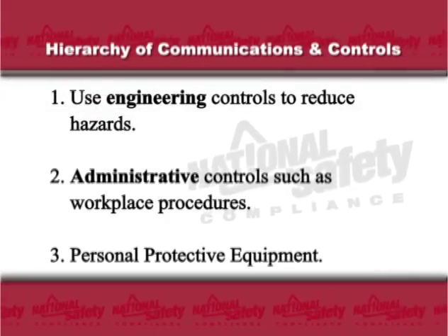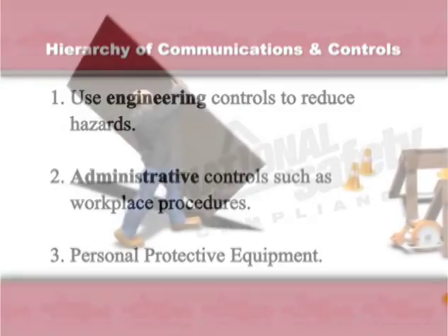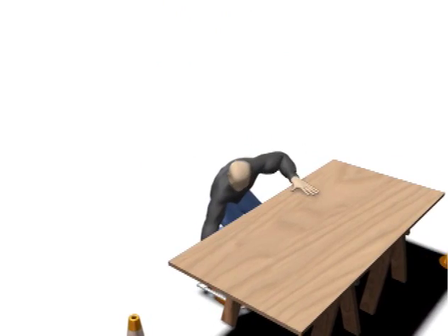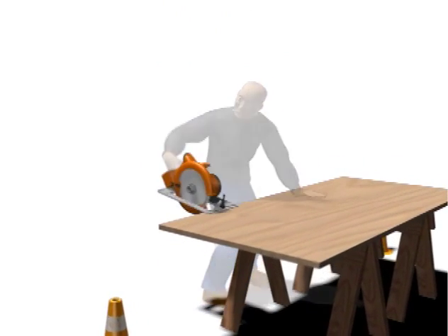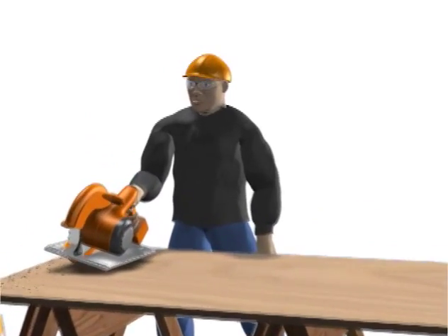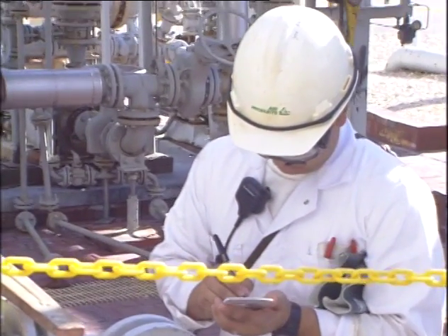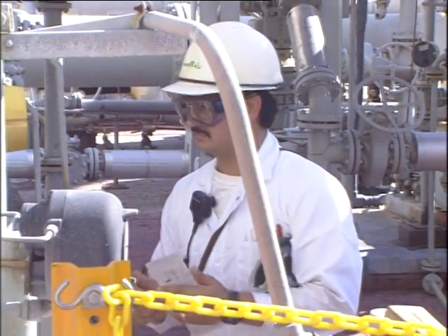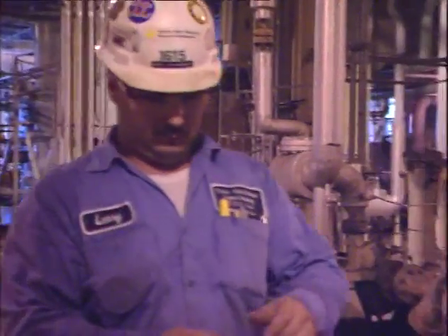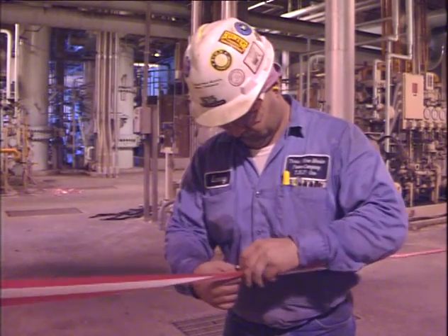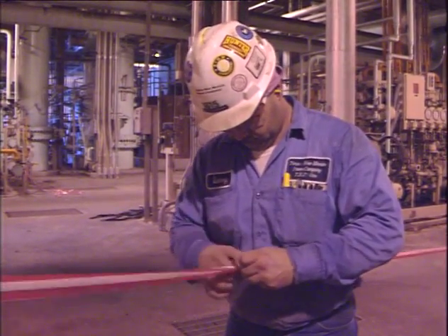A commonly used practice, referred to as hierarchy of controls, is effective for addressing hazardous risk. Start at the top and see if the hazard can be controlled with engineering controls, taking the employee out of the equation. Then factor the employee back in by changing the way they work, how long they work, and using PPE. The hazard assessment should be conducted by the company safety officer or other qualified individual to identify the sources of hazards. Hazard should be determined by assessing the tasks involved, the employee performing the tasks, and/or group of employees, especially if the group performs identical tasks.